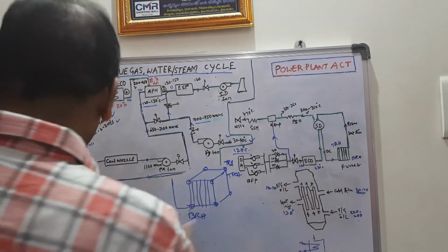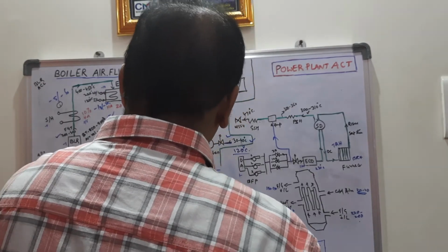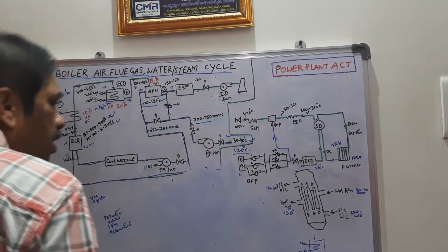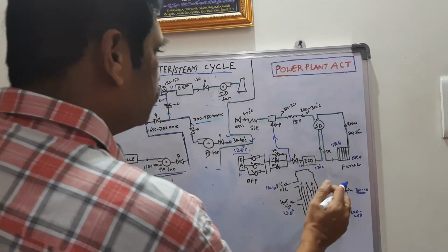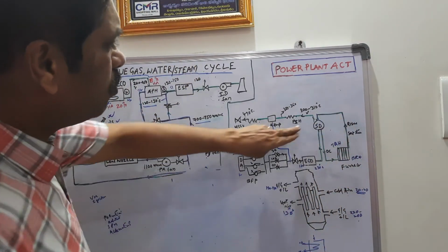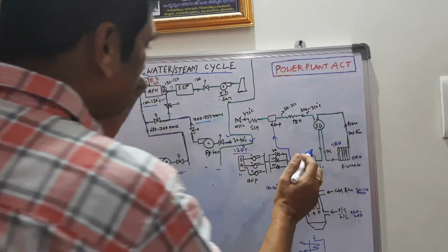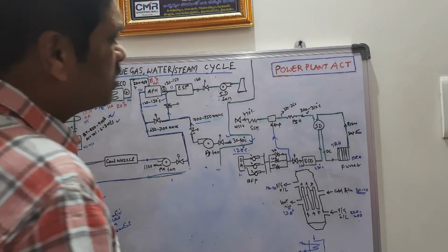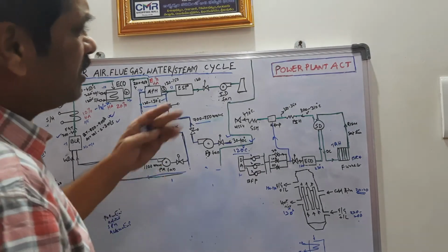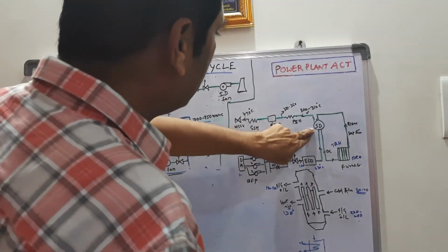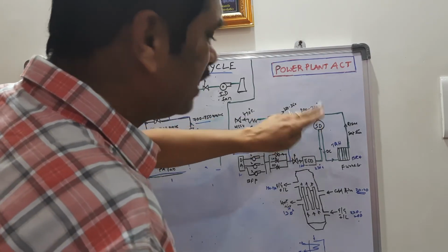After the top ring header, it enters once again the steam drum through riser tubes. In the steam drum, a separator is provided inside, where steam and water are separated. Only saturated steam comes out and water is retained inside the steam drum.